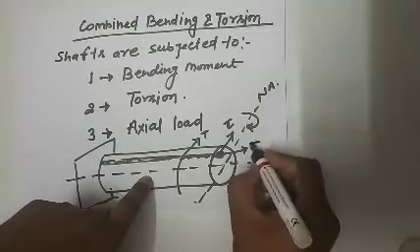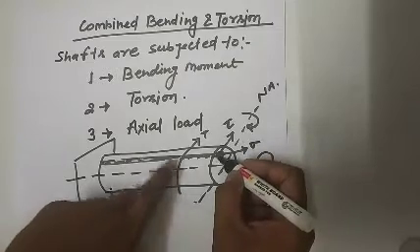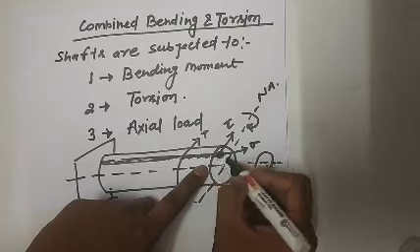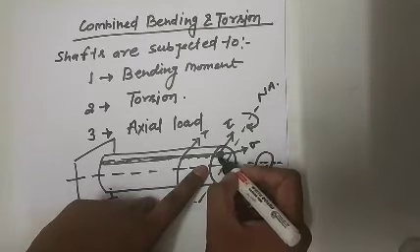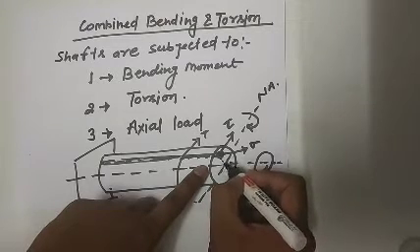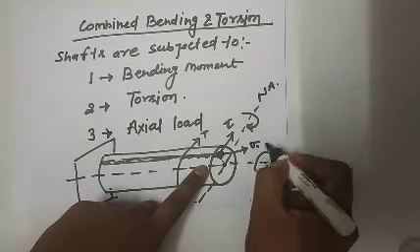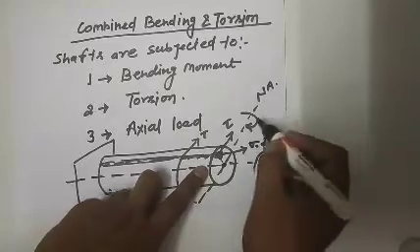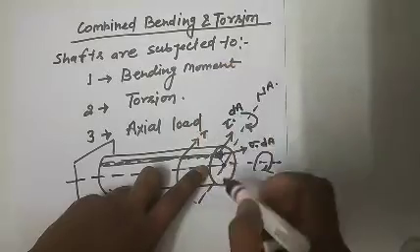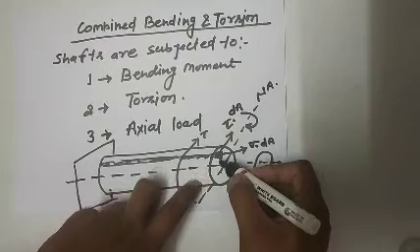If we study these things by the force generated by these stresses, then say the elemental area of this layer is at a small distance from this centroidal axis, from this centroid. The bending force generated will be sigma into dA, and the shear force generated will be tau into dA, where dA is the area of cross section for this portion.